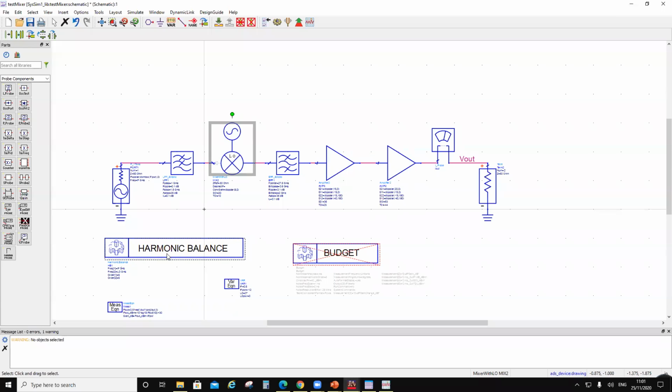So how is the gain decided? Let's say I have a DAC here, which is going to give you an analog output, and that analog output is like minus, let's say, minus 20 dBm. I have to deliver 30 over here. So this is minus 20 over here, this is 30 over here. So the overall gain of the chain would be 50.